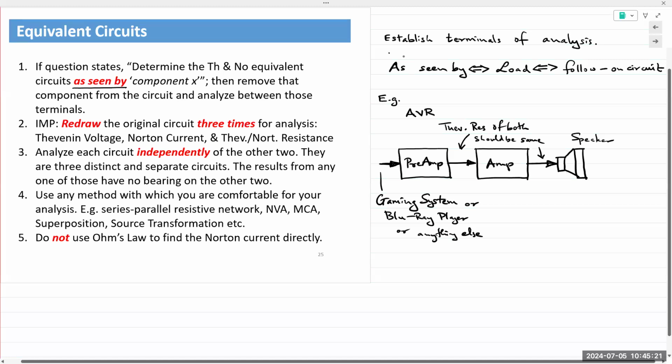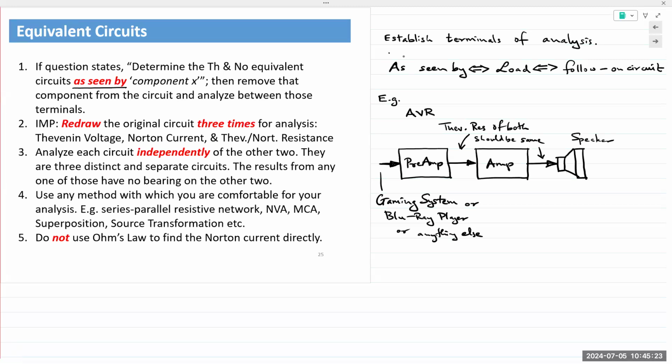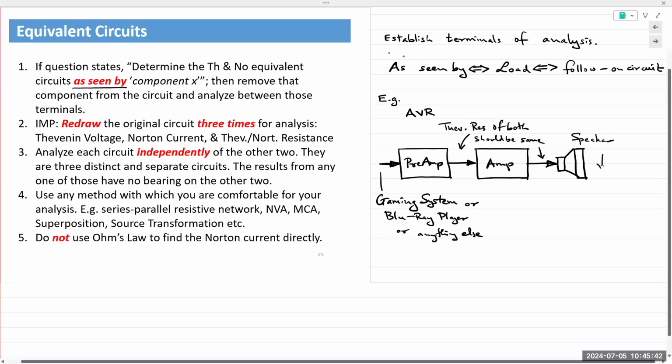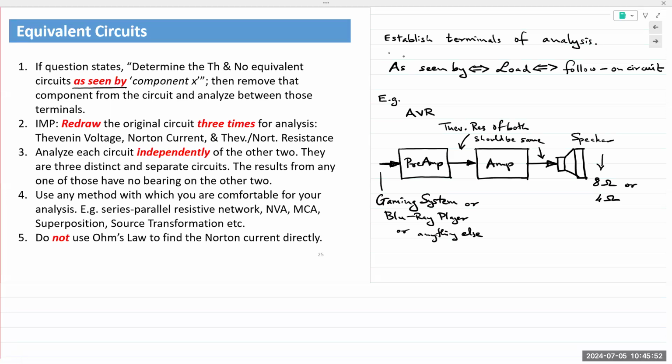If you look at the output of any amplifier system, it'll always tell you that it can drive, say, 100 watts into an 8-ohm speaker. If you're buying speakers separately, the speakers will have an impedance. It basically tells you the impedance or the resistance of the coil of the speaker, which is typically around 8 ohms. So speakers in real life have 8 ohm or 4 ohm impedances or resistances. So the output of the amplifier is matched to the particular speaker.